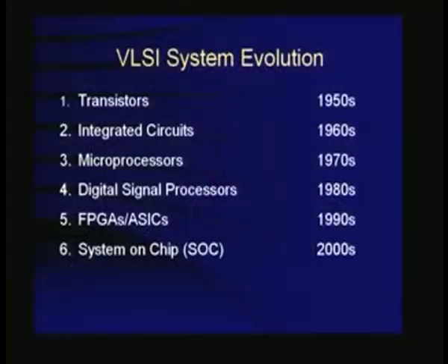So in that sense, microprocessor and DSP have a commonality. Similarly, DSP, FPGA and ASICs have commonality in the sense they are functionally related, but a DSP is programmable and can be used for different functions, whereas FPGAs and ASICs are meant for a specific function. So the FPGA has the advantages of an ASIC and of a DSP: the programmability of a DSP and the architectural, innovative features of an ASIC, both put in one.